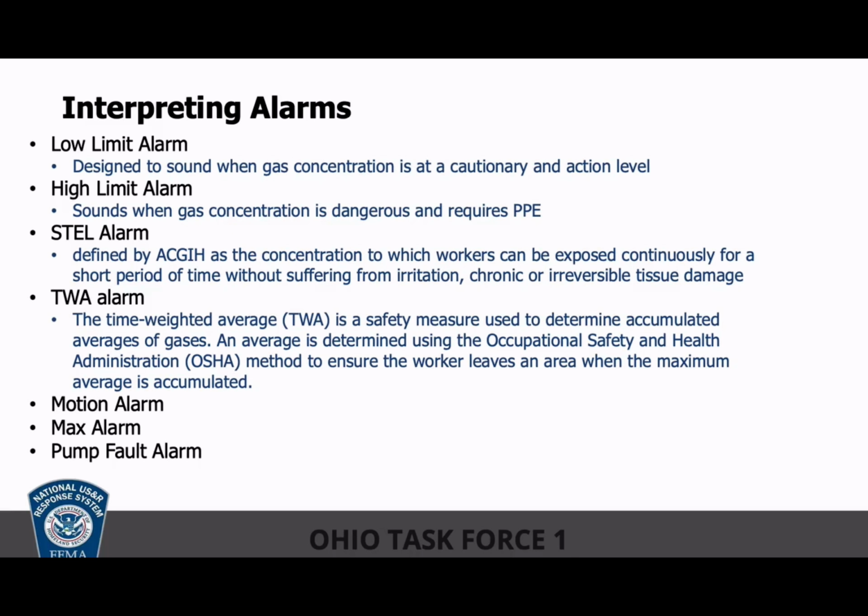10 parts per million is pretty easy to get to in a 1,000 parts per million concentration of a toxic chemical. So as a hazmat responder, you need to be smart enough to get into that meter and turn off those alarms by changing alarm limits for mission-specific needs only. For general non-protective USAR, personal, and fire department work, we never change alarm limits because they're set there to keep you protected.